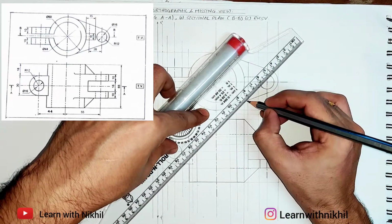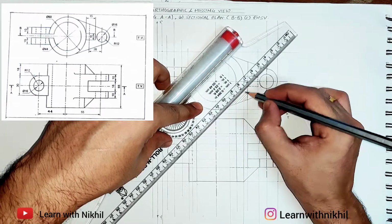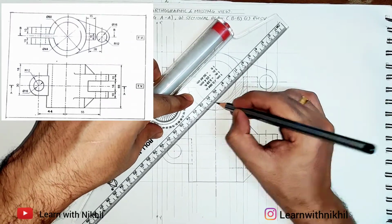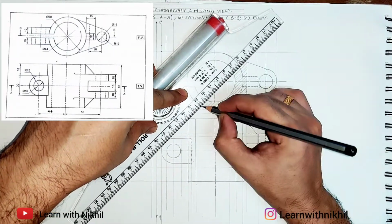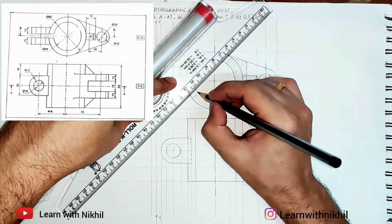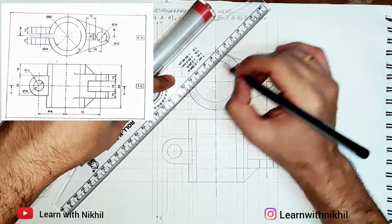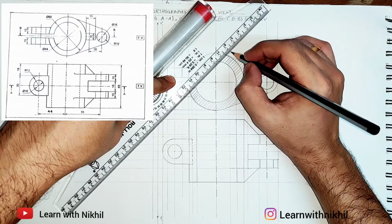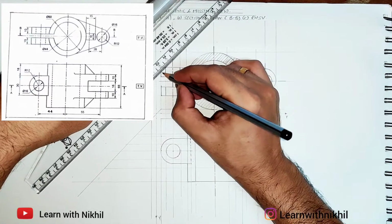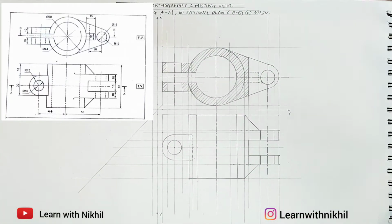I am drawing the section lines for the front view. So the right hand side part, after the section it is totally visible, so that will not be sectioned. The inner circle will be a whole shape, so I am not drawing the section lines there. Here also section lines, the circle at the center is not sectioned.